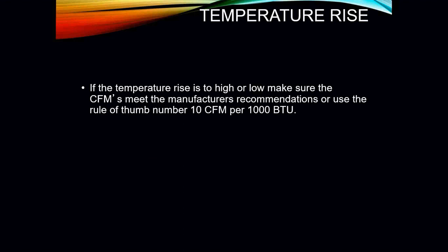And if the temperature rise is too high or low, make sure the CFMs do meet the manufacturer's recommendation. Or if you don't have the literature, or you can't read it, or it's missing, or what have you, you can always use the rule of thumb of 10 CFMs per 1,000 BTUs of heat.